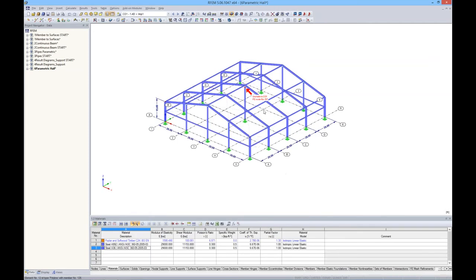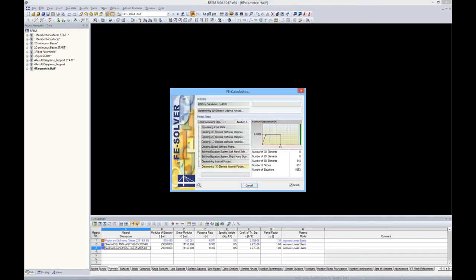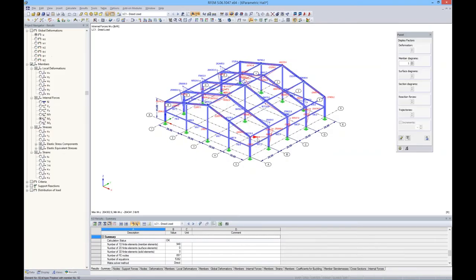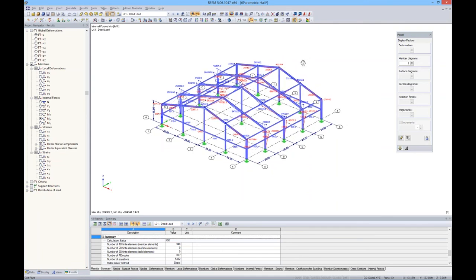I say, okay, now I need to address this. So with load combinations, everything is run according to a nonlinear analysis, taking into account P-delta effects. But load cases are run as a linear analysis. Only load combinations will apply those P-delta effects as a nonlinear analysis and adjust that stiffness matrix. So for load case 1, dead load, I want to run it just to make sure that maybe my geometry is okay, I don't have any nodes not connected. I run it, and everything runs fine. You can see here that I have my results diagrams pop up for my moments about the local y-axis. So, okay, it has something to do with those secondary effects.